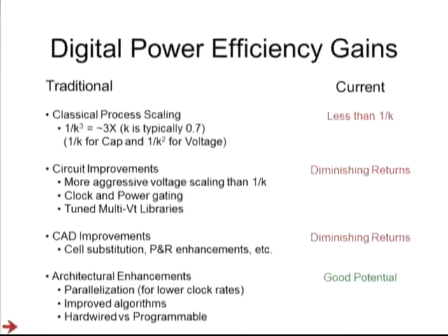On the circuit side, we've done a lot and accomplished a lot over the last few generations, scaling voltage even more aggressively than the technologists to a degree. We've incorporated clock and power gating, tuned multi-VT libraries, etc.